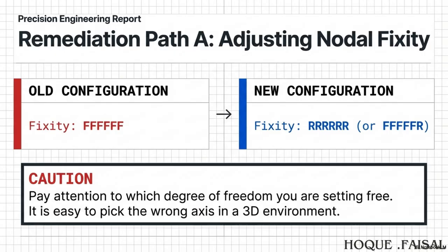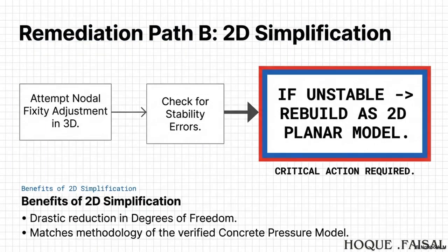And there's a number here that just jumped right out at me. Let me guess. The member 2 displacement sum. That's the one. The movement of the main vertical beam peaks at roughly 0.077 inches. 0.077. That is less than a tenth of an inch. Just think about that for a second. Yeah. You have a structure that is 2 stories tall. It's being hammered by an 81 mile per hour storm. A near hurricane. And the computer, this incredibly sophisticated piece of software, says it moves less than the thickness of 2 credit cards stacked together. My immediate reaction is, wow, that's an incredibly solid wall.